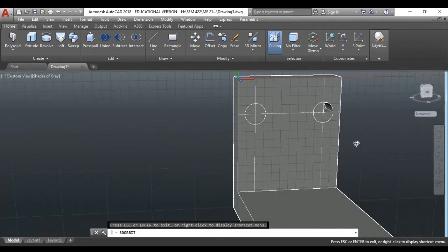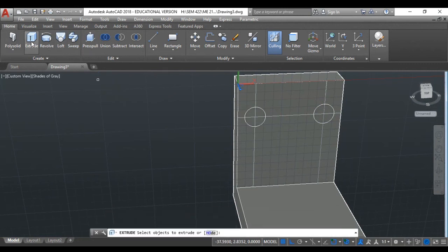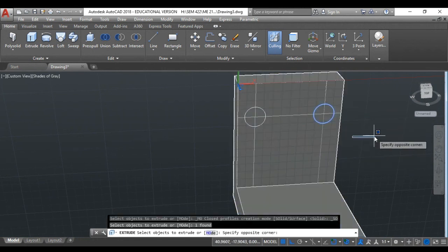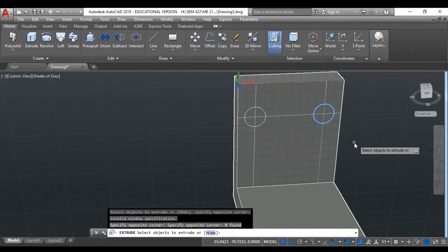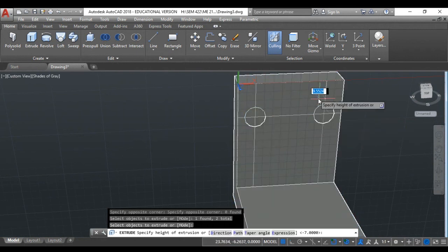instead of saying, well, I'll just do it quarter by quarter, our main business is how to save every single second, right? So what we need to do is, before you think about your extrude, maybe if I use extrude it will work. Let's see. In that extrude I'm gonna select the circle itself, okay, and then after selecting the circle, select object extrude. Let me choose this one also for the circle, and then right click, and then